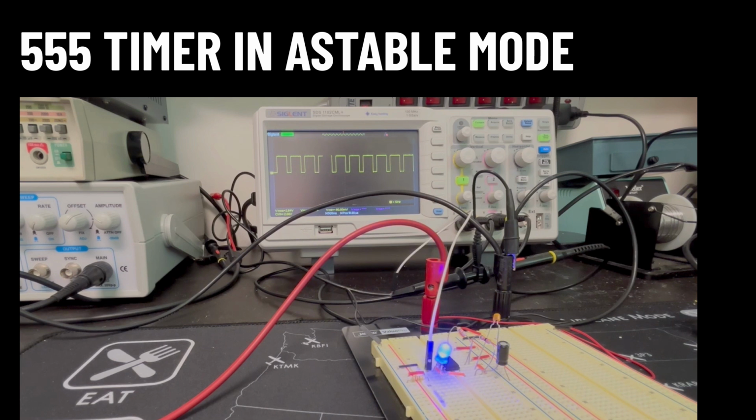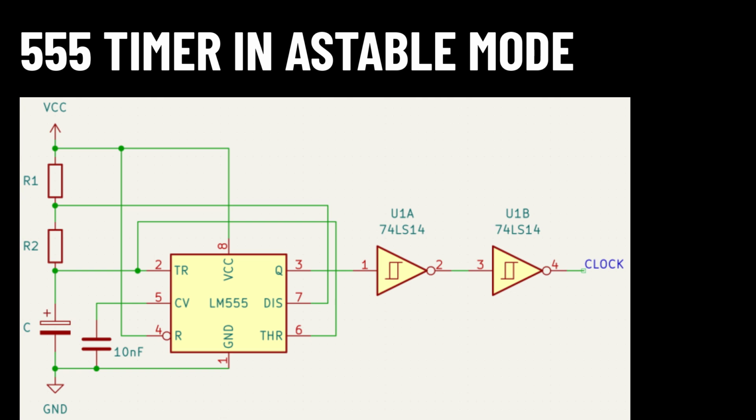If you have a circuit that you're sure you've built correctly, but sometimes states in your finite-state machine or counter circuit are randomly skipped, then your 555 timer output signal may be to blame. To fix this, use a 7414 Schmitt inverter chip on the output of your 555 timer. This will correct any voltage levels to the appropriate TTL-compatible levels.